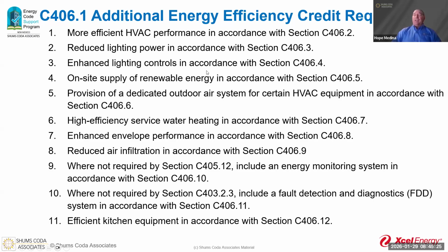That we have the enhanced lighting controls. That's another credit. The on-site, so solar photovoltaic, wind generation. Do we have any renewable power on site? That gets a credit. Outdoor air systems dedicated for the HVAC system. That gets a credit. High efficiency water heaters. Those work well. The enhanced envelope performance. So we beefed up our insulation. We beefed up our infiltration. Right here, the reduced air infiltration.